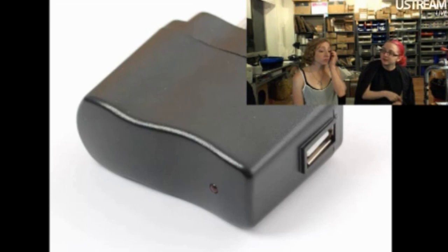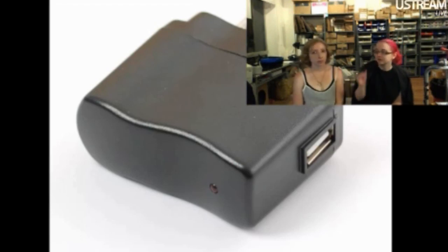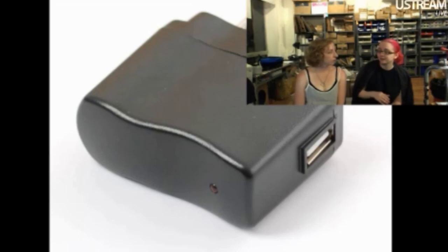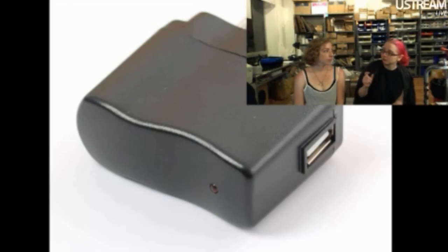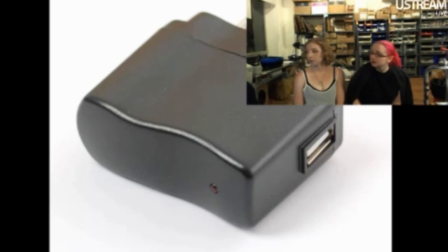Yeah. So by the time it gets to the cable and through, I think there's a diode or something, the voltage drops just enough that it can add flaky behavior. So people have actually posted about it, like, you really want this adapter that has just a quarter volt more. So by the time it gets to it, it's like 5 volts perfectly. Will this work with Raspberry Pi? Will it work with an Arduino? It'll work with anything. Anything that wants 5 volts in, you can use.